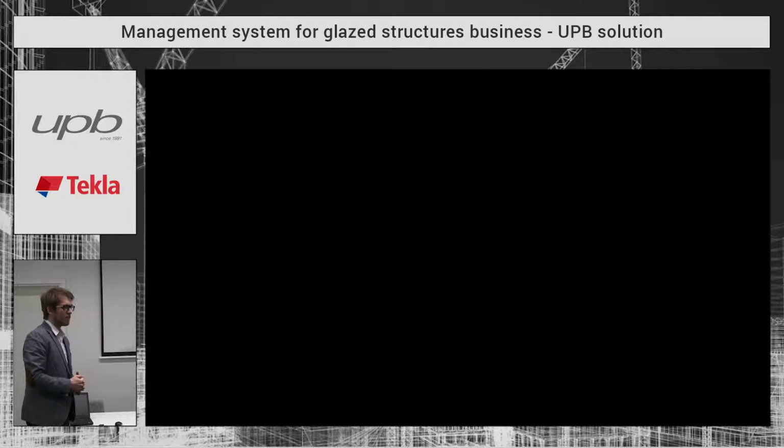Another thing is it does automatic numbering, where it can compare size. For example, you draw 600 elements, and Tekla can tell you automatically which elements are the same, with the same number. And if you change something afterwards in the model, Tekla will automatically recalculate and give you the changed amounts. Drawings and revisions update automatically, nothing is done by hand.